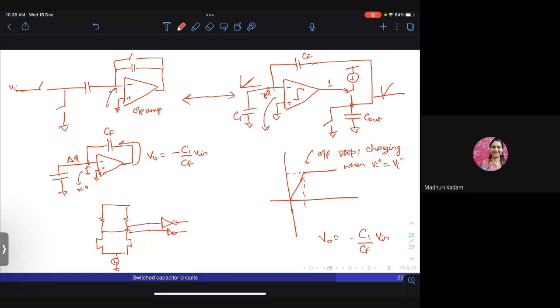Using an inverter to take a small differential voltage to rail to rail signals as an amplifier will never work in an op-amp, right? Because it's very difficult to control the operating point and all. But here you don't mind about all those things. So the type of comparator that you need here can be easily made even in digital CMOS processes.